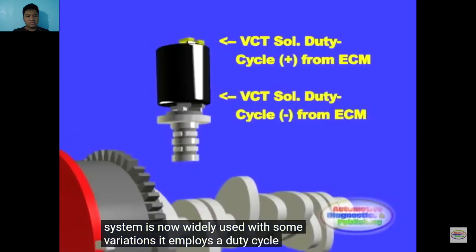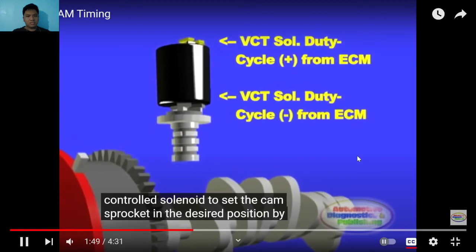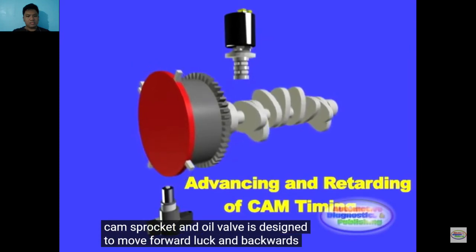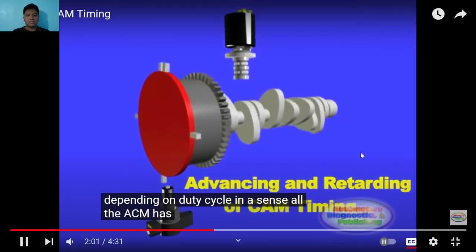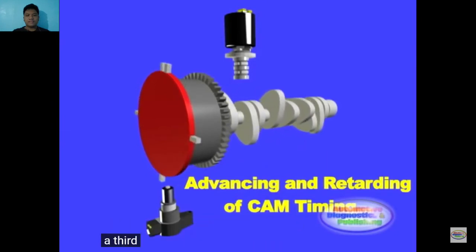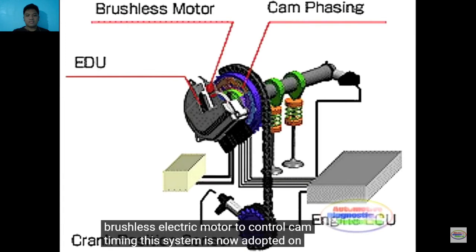It employs a duty cycle controlled solenoid to set the cam sprocket in the desired position. By controlling the duty cycle exactly, the cam sprocket and oil valve is designed to move forward, lock, and backwards depending on duty cycle. In a sense, all the ECM has to do is control the duty cycle in combination with the cam position sensor. The third system is a fully electrical variable cam timing, which uses a brushless electric motor to control cam timing. This system is now adopted on Lexus vehicles.